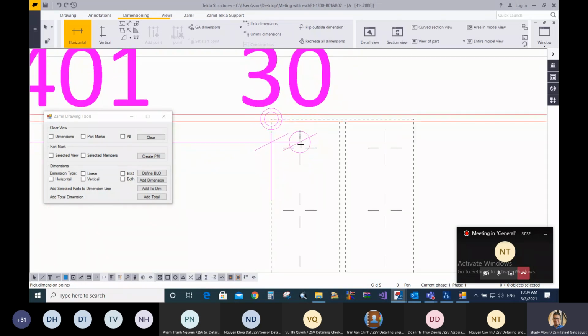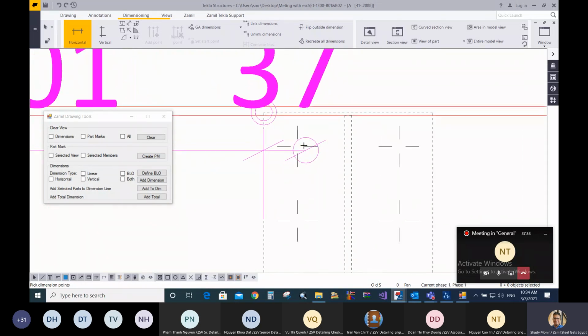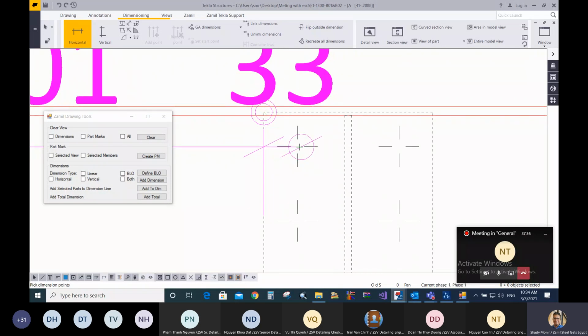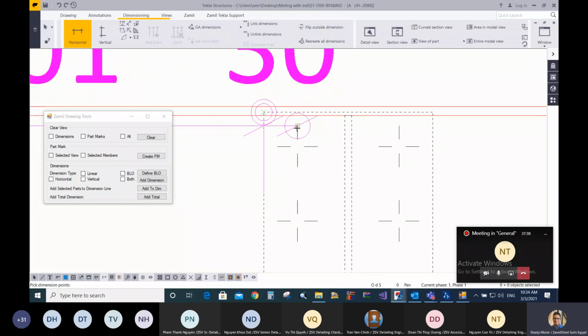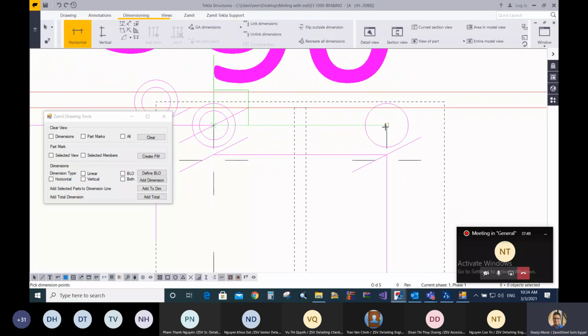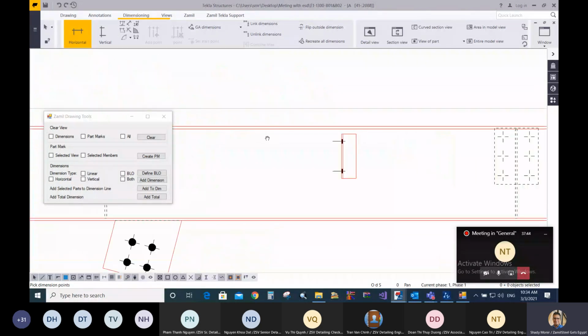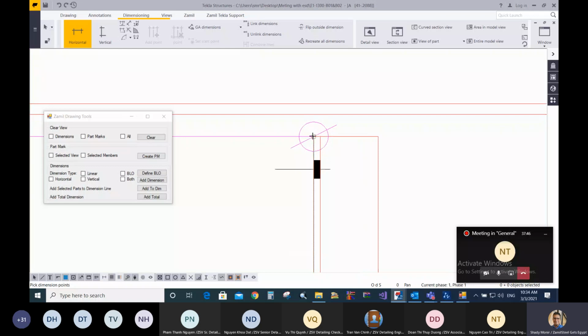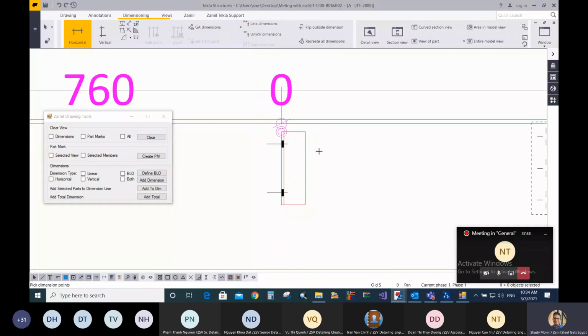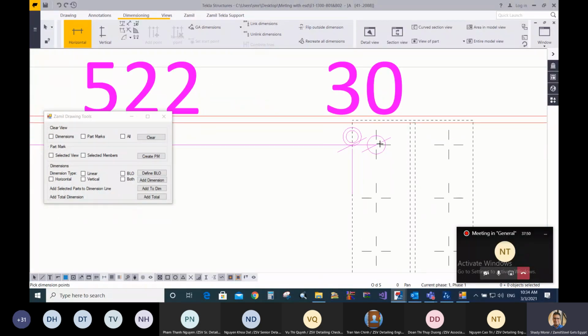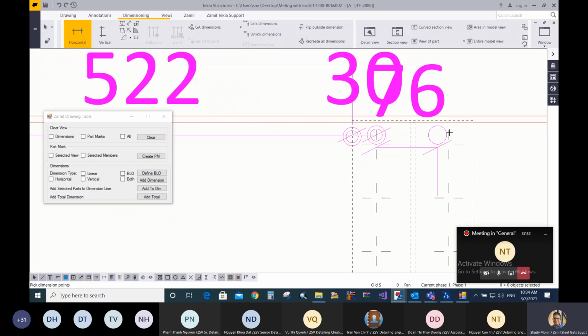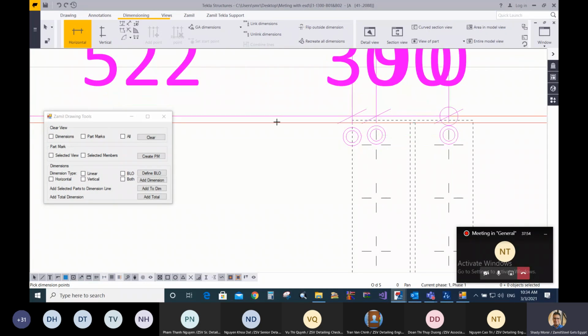So as you can see, if I want to select the bolt, I have multiple selections, so this may cause an error, and so I have to zoom in to select the correct location, and then go ahead. You need to fix this item also, and you need to fix these edges, for example.